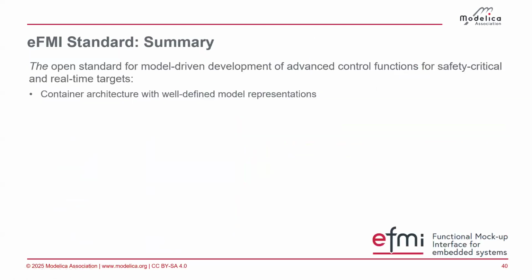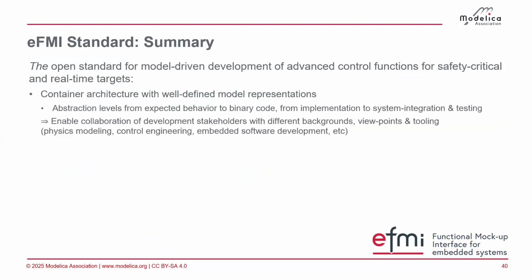So in summary, if you think about the eFMI standard, it's, in my opinion, the open standard for model-driven development of advanced control functions for safety critical and real-time targets. It has a container architecture with well-defined model representations on the different abstraction levels. It has the abstraction levels from the expected behavior to the binary code, from the implementation to system integration.